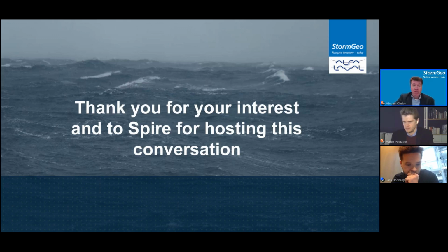I can start with that too. Yeah, I mean, the CII includes your at sea, your maneuvering, and your in-port consumption. So absolutely, and as Marek was showing, lengthy times in port can actually be detrimental to your CII, where you're not moving yet you're still consuming, because the distance is in the denominator of the equation. Then consumption without any additional mileage is going to ultimately penalize you a little bit in your CII.